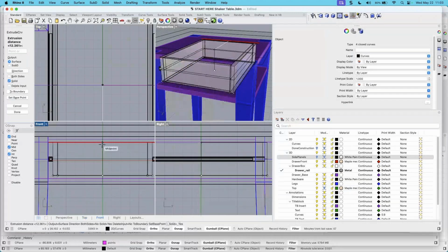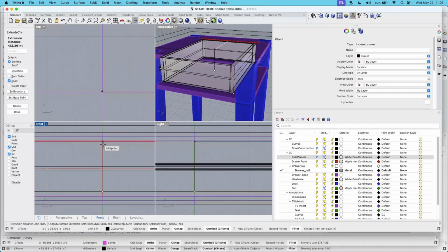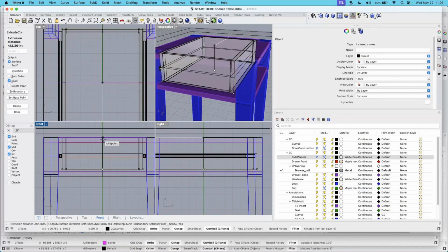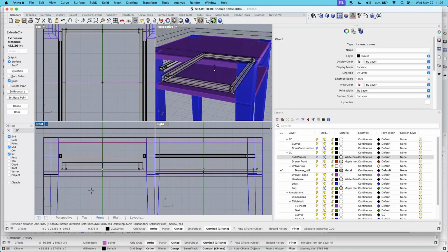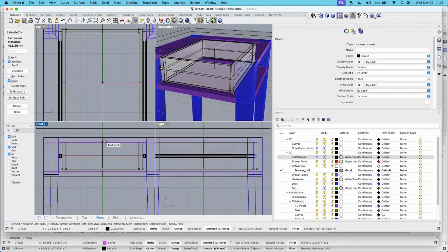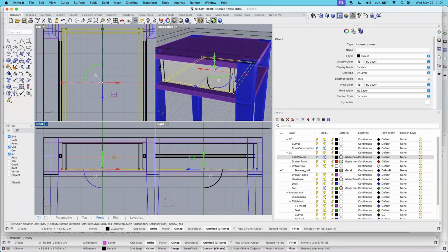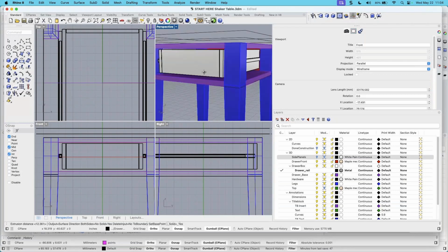And let's come up to the height of the drawer. Now, the height of the drawer to the top of the panel is 3.5 inches. So what we may want to do is just something under that. I'm looking down here in the status bar to get that number, 3.666. What if we put in 3.5? That would probably work just fine. Okay, so we now have the sides of the drawer.